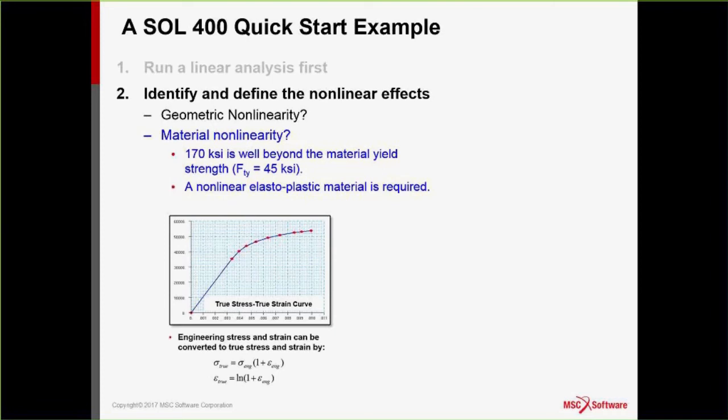So in this case, I'm going to enter a stress-strain curve into Nastran. Nastran Solution 400 thinks in large strain because it needs to handle very large strain. So we want you to enter true stress versus true strain in this case. Many of you will actually get stress-strain data from engineering handbooks. They come as engineering stress and strain.